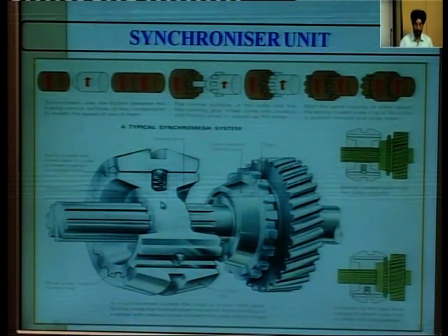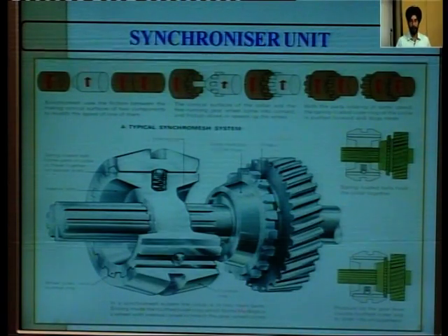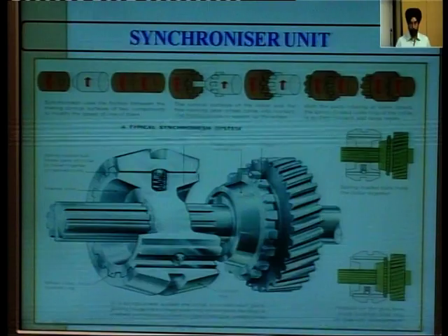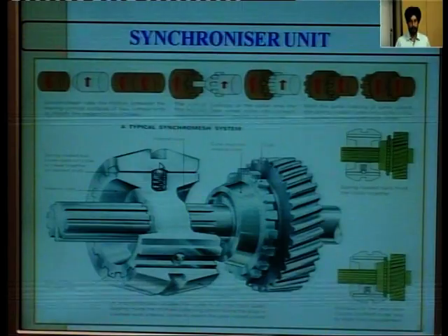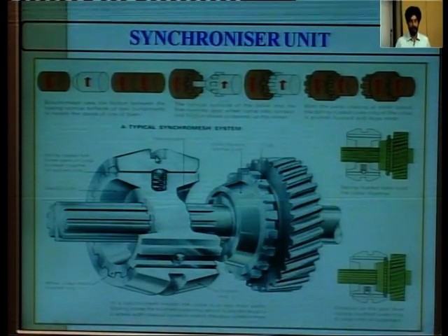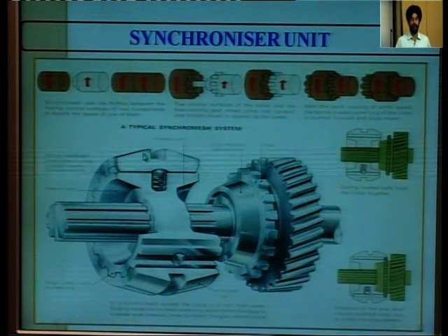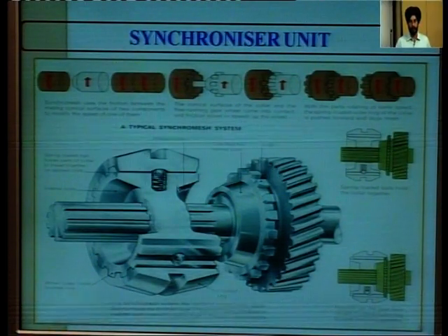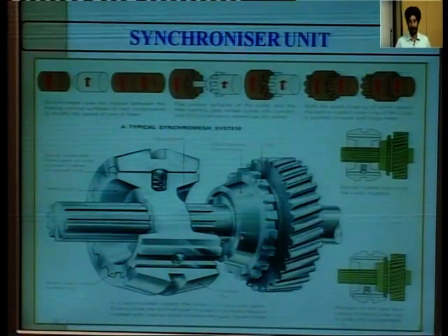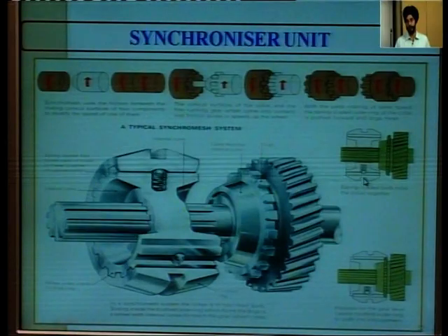Now, this is the actual construction of the synchromesh system. This is a gear on the output shaft attached with the dogs on the sides, with the side periphery having the conical surface, and this is the synchromesh system. Here is a slot in which the lever is placed to move towards the gear, and when the gear is engaged, this whole assembly moves towards the right, towards the cone. Say, in this condition, the whole synchromesh unit has moved near the